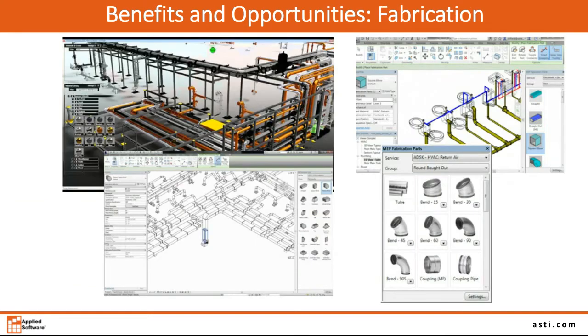With the building information model, fabricators can now fabricate duct runs, pipe spools, and fittings, and they can do this off-site and then deliver that to have it installed on-site, decreasing the time it takes to construct the building, reducing errors and clashes between systems. And in addition to that, the contractor can use the building model to extract critical locations for things like pipe hangers, pipe stub-ups, etc., and locate those with extreme accuracy on the job site.